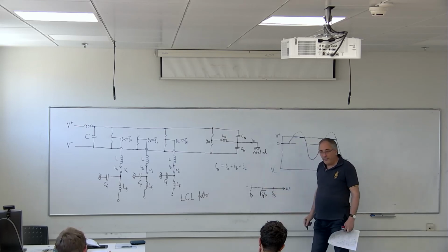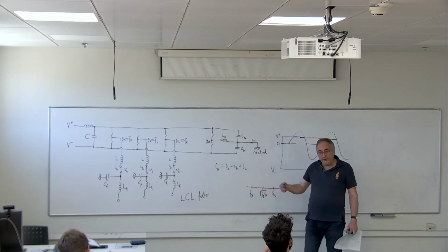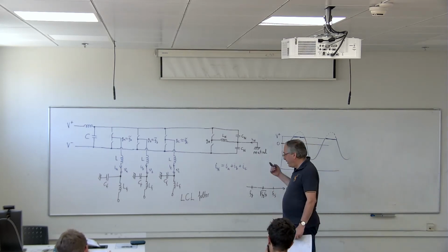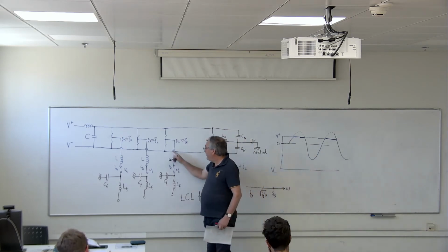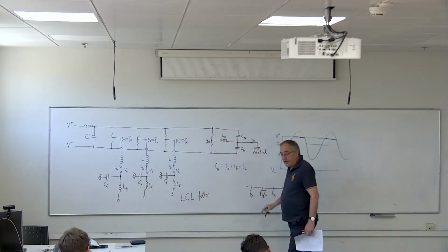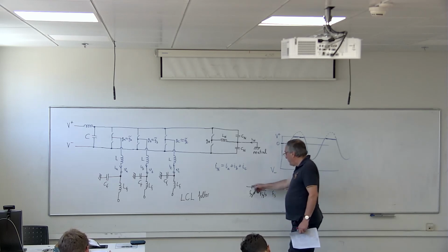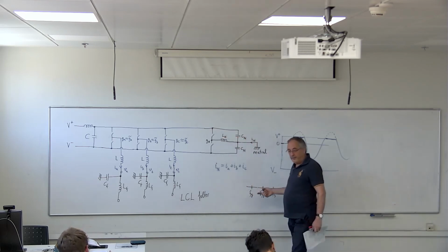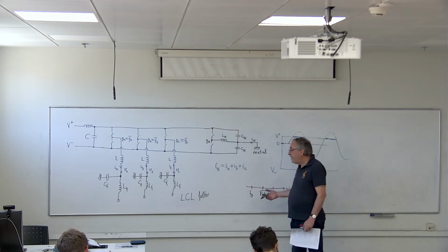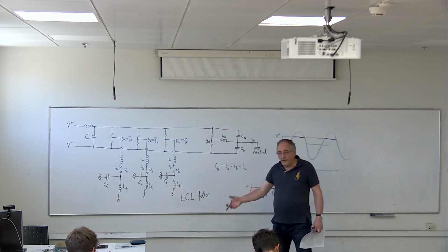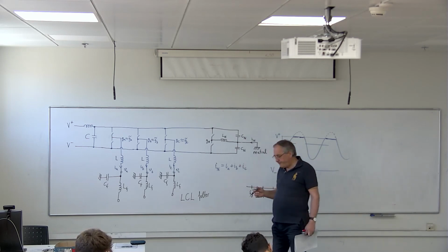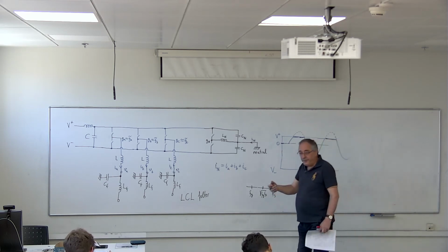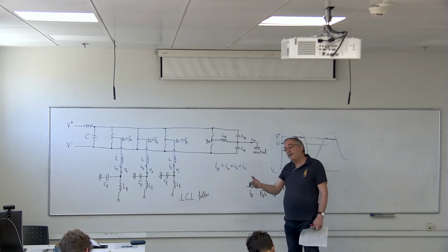If that is not clear to you, why on a logarithmic scale the midpoint between 2 points is the geometric mean between those two. Now, why do you put it in the middle? Why the resonant frequency? Because you want to generate low frequency voltages at the frequency FG. So if the resonant frequency is significantly higher than FG, then your signal will not excite the resonant frequency of the filter. Between 50 hertz and 10 kilohertz, the midpoint is roughly 1 kilohertz, right? So the 50 hertz signal will not excite the resonant frequency of 1 kilohertz in your filter.